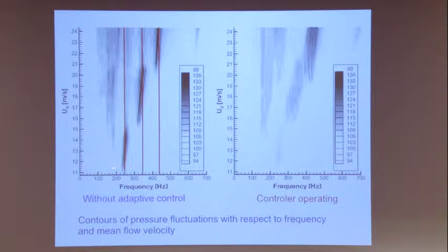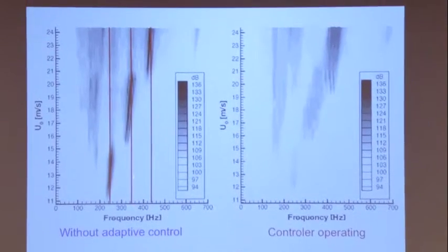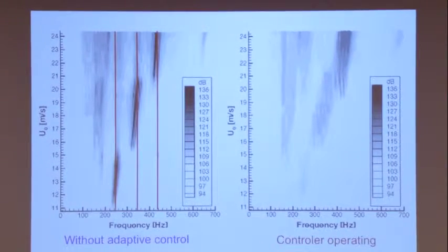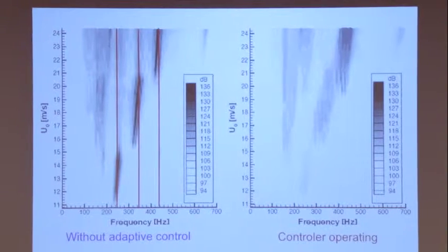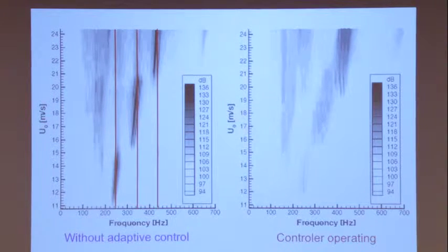And this is a plot of the frequency that is observed in the system as a function of velocity in this test section. And you see that certain frequencies appear at a strong level in decibels. You can have pretty high values at particular frequencies. Of course, the device is much smaller than the rocket, and so the frequency is multiplied by the scaling between the two.